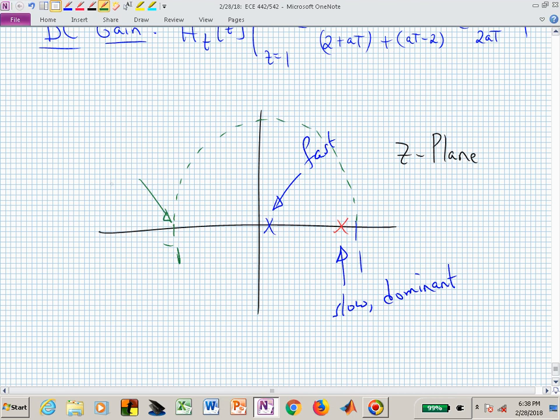We are now up to omega sub s over 2 in terms of frequency, the Nyquist frequency. And so you could think of that as being fast in a frequency sense. If you're now shaking, this system is only really going to shake at that high frequency, omega sub s over 2. So you kind of have two different fasts to think about in the z-plane. And I wouldn't try to make one absolute and the other one dismiss it. You just kind of have to keep those two things clear in your head.